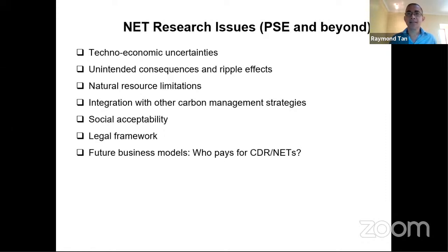Now, another key issue, which I don't know if my former student, Dr. Bea, is here in the audience, is that we look at some of the risks associated with biochar application. That means that the biochar, depending on how you make it and on the feedstock that you use, could contain contaminants that you would not want in excess amounts in your soil. That would include, for example, byproducts of the pyrolysis process, such as dioxins and furans, which are on the surface of the biochar, but also content which was originally in the feedstock. So you could have heavy metals present, or more innocuous but still problematic salts. And if you put too much of it in your soil, then you begin degrading the quality of the soil if it's used for agricultural purposes. So those are the two main issues.